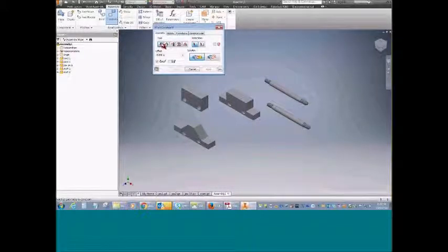So I'm going to talk about all these different constraints to some extent. In Inventor, my mate constraint does 90% of my assembly. The angle constraint is there. Use that at times. And then I have a tangent constraint, an insert constraint when it's just real straightforward, a round pin and a round hole. And then I have some symmetry I can build. Two different solutions for especially the straight mate constraint.